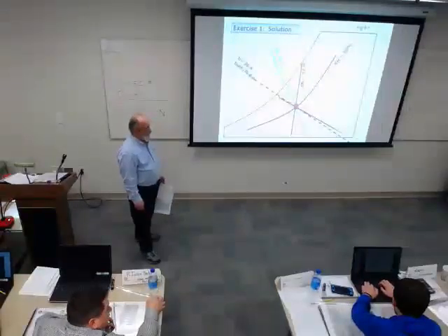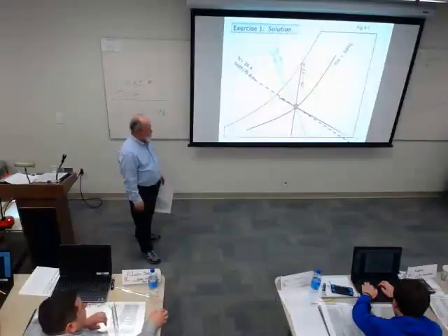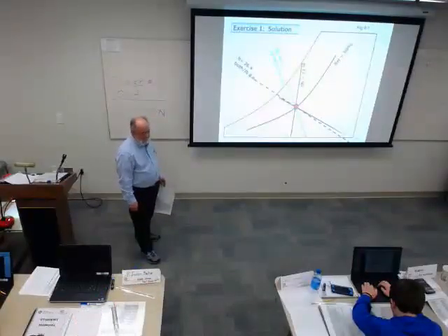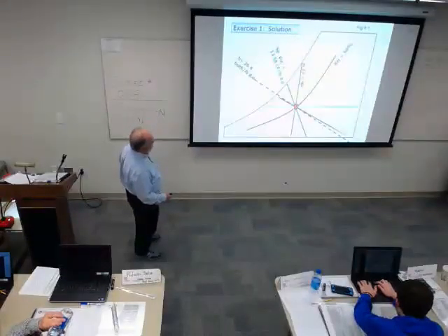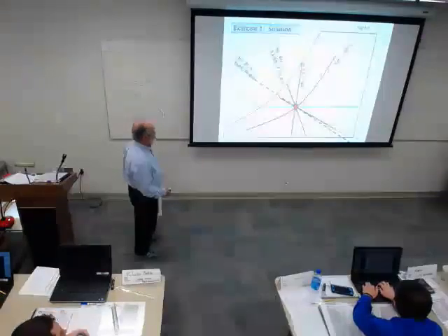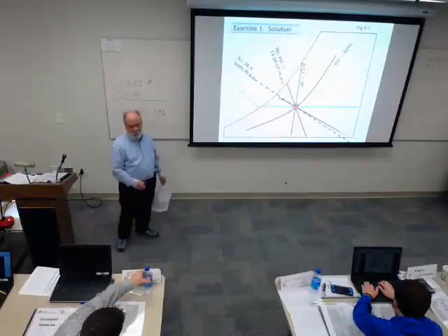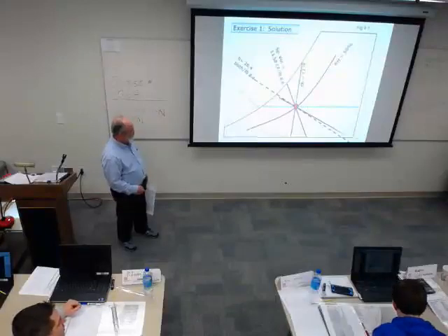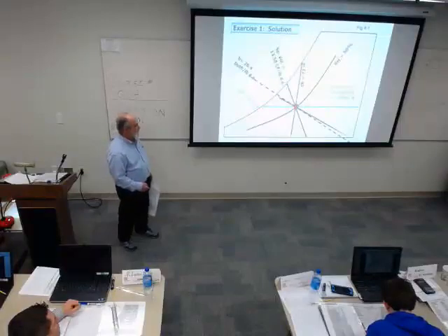Just so everybody gets what we're doing in case this got missed: what we're trying to show you here is that once you know any two points, you know all the rest of these. We're just going over where each of them are. So you can use any two to find the rest. Once you get that point, you find the rest. So we got that, and we can extend the line over, and we discover that our dew point is 52.2. And as I said, that is going to be exactly parallel with the next one here. Absolute humidity.